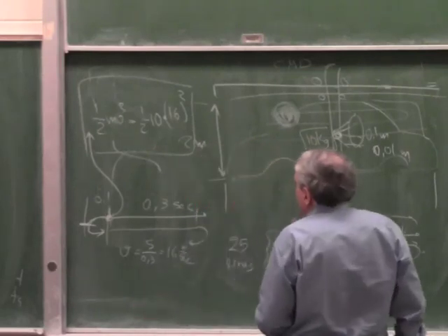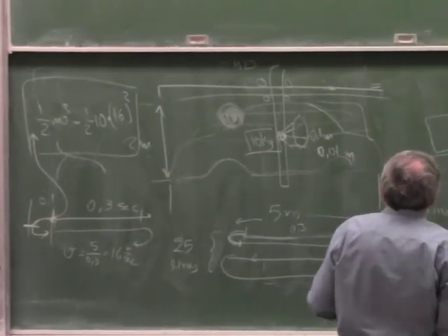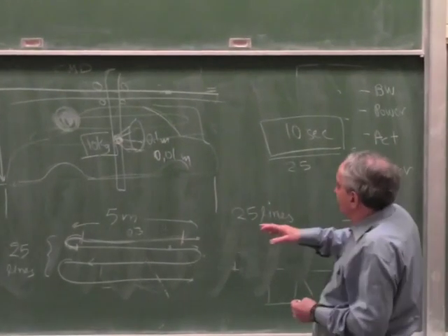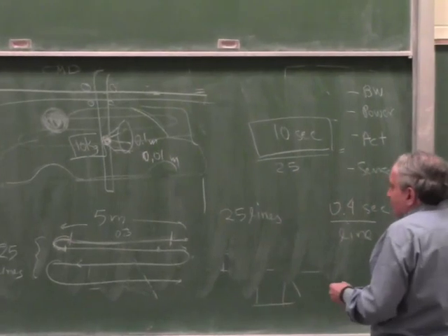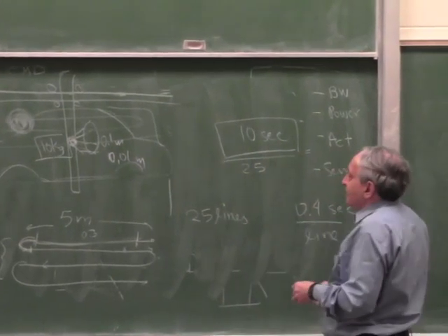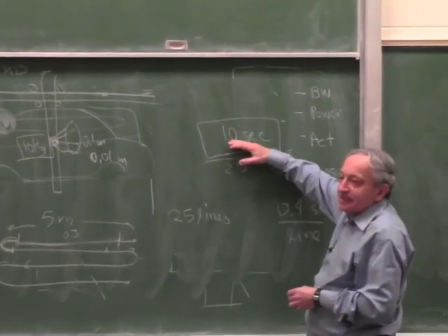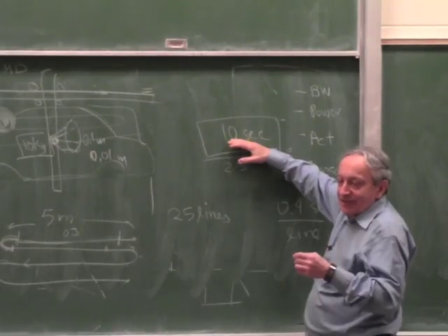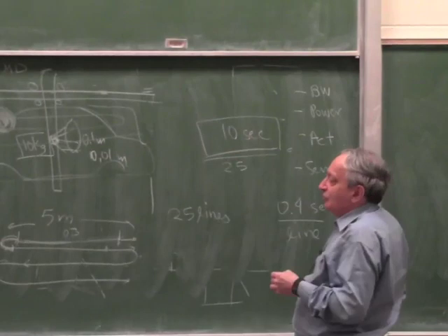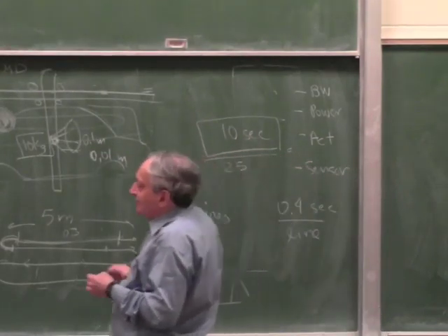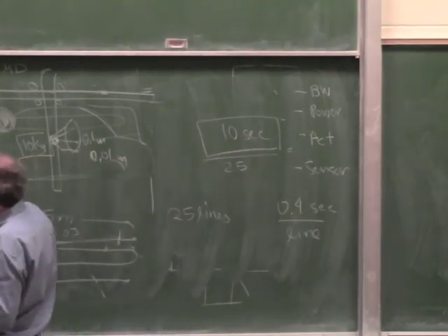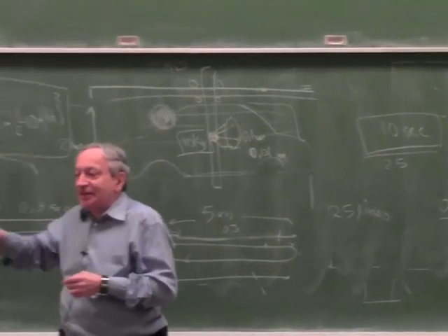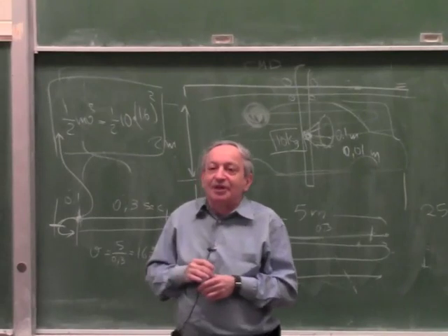Okay, if you want to know the power, a line is 0.4 seconds, so 2.5 times a second, because you have 25 lines in 10 seconds. So 2.5 times a second, you have to decelerate and absorb 1300 joules, and then accelerate and output 1300 joules, but we count it as the same.